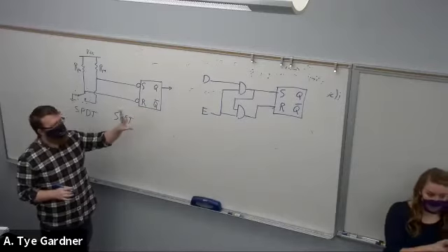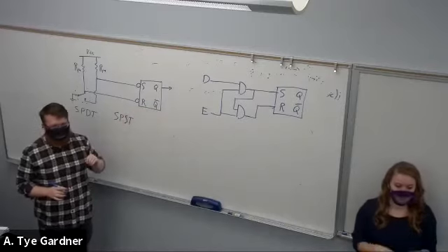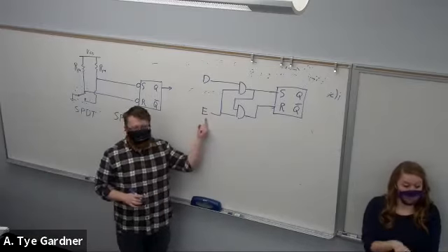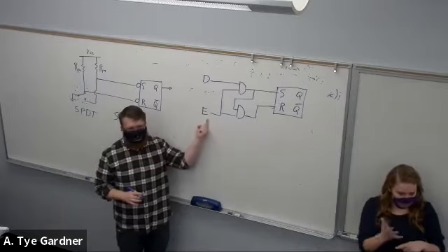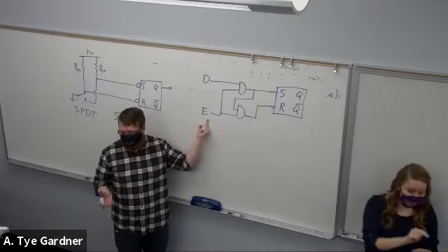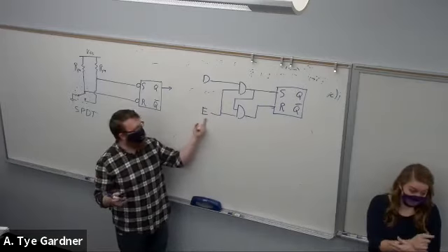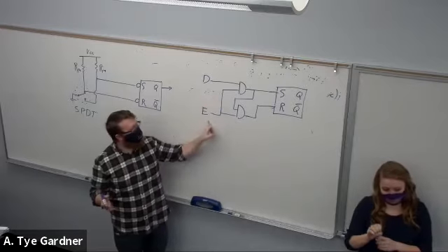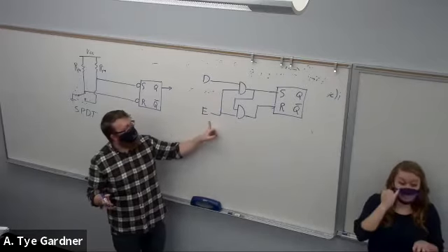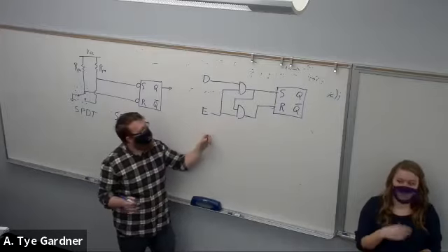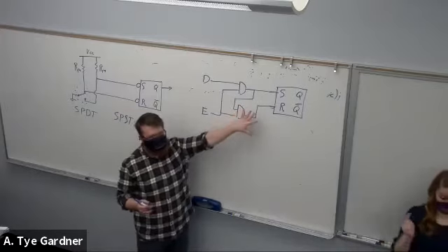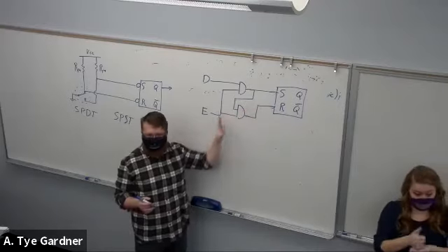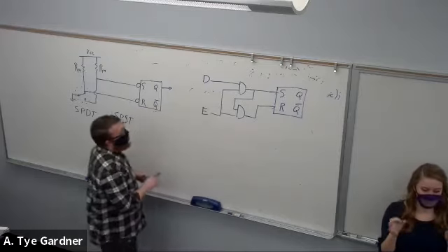Now it's a little bit easier to talk about this circuit in just the AND gate. So the AND gates are just functioning as the enable gates. We can just turn it on or off with the enable, right? That's what AND gates do, one of the functions we use is to add an enable to something. We can only pass data if it's enabled. Now we also have the benefit with this cross coupling that we don't have to worry about the set and reset being different. There's this kind of feedback preventing us from having issues.